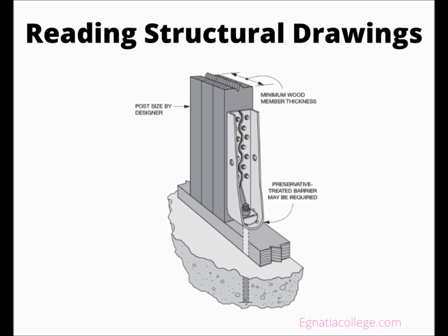Once the concrete is placed, the concrete is allowed to partially cure, usually about 7 days or until a specific compressive strength is achieved. One end of the tensioning cable is then anchored and a hydraulic tensioner is used to stretch the cable inside the slab. The plastic coating allows the cable to stretch inside the now solid concrete. The cables are tensioned to approximately 33,000 pounds.